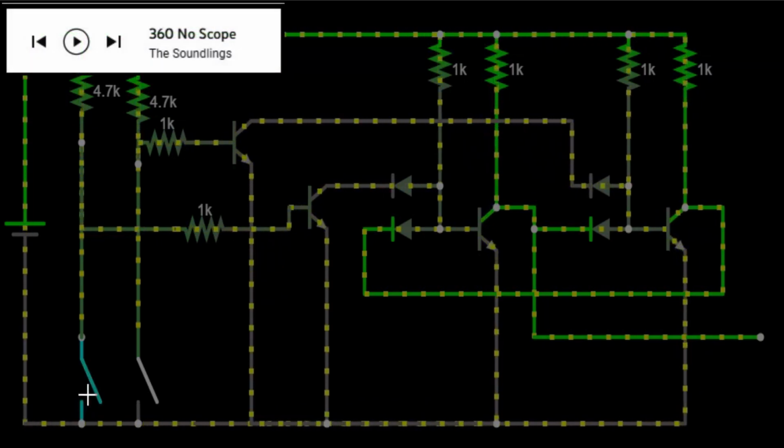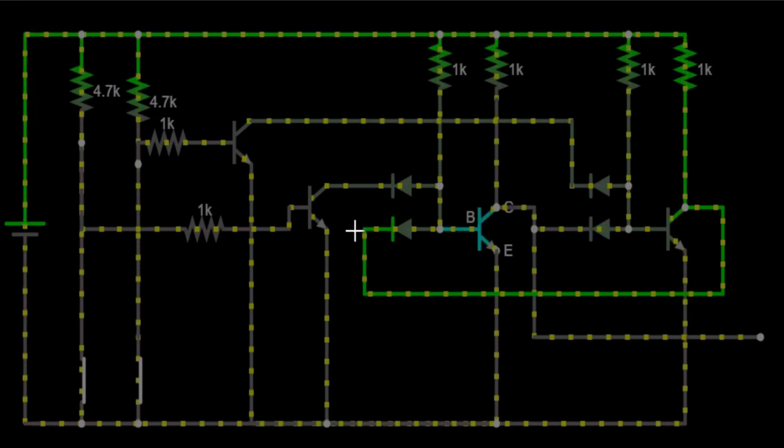Okay. That seems to be working. It's set. Turn the output on. Then reset, send that high, turns the output off. Okay, so that's the basic circuit for a SR flip-flop. 4 transistors, 4 diodes, 4 resistors, plus an extra 2. That should be it for that.